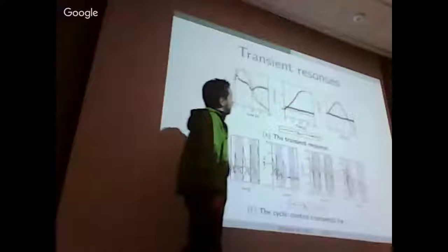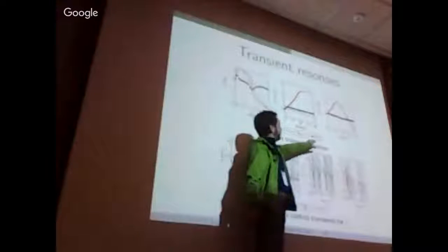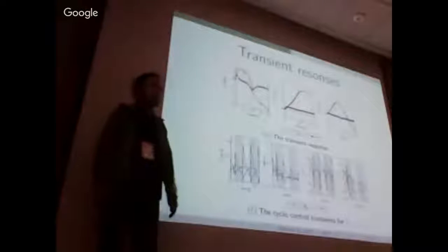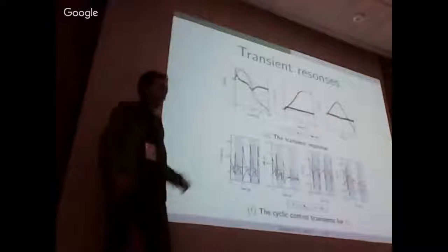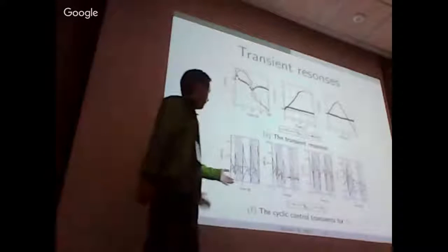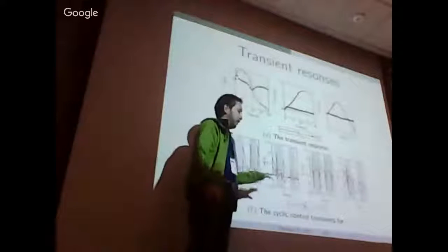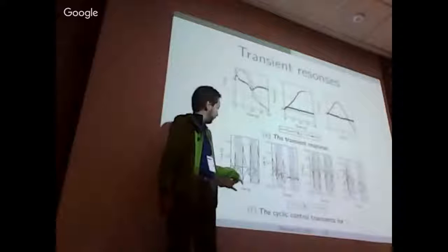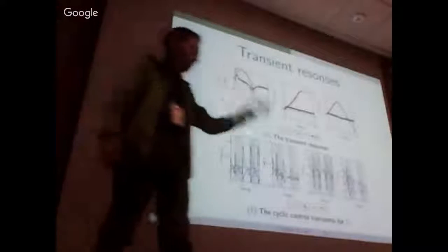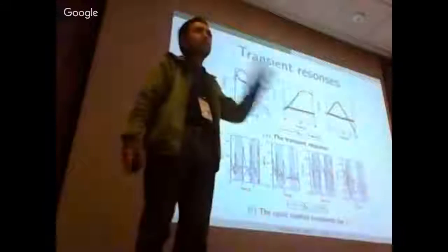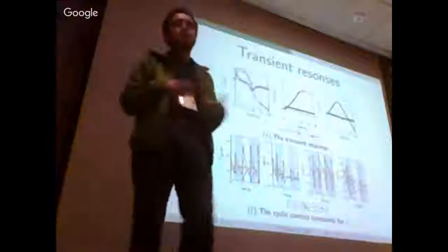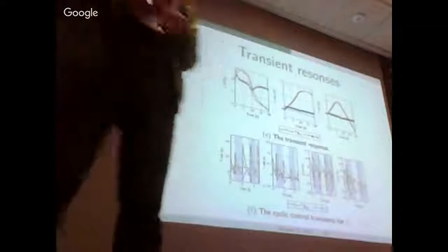That's it. I also show you the control command, and this is the cyclic control transient for the walking pattern. You can see that each time the phase shift is triggered, the control command for the swing tripod increases in magnitude, and then decreases when it almost reaches the desired position, and then a phase shift occurs, and this cycle pattern repeats itself.